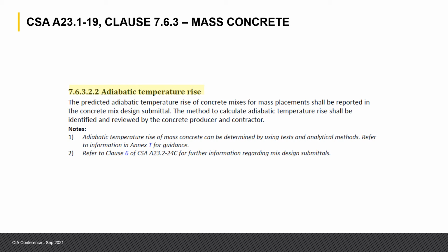So now we have a requirement that the mix design needs to include the adiabatic temperature rise associated to that combination of materials. Even when they do not report the actual proportions of materials, you need to provide the adiabatic temperature rise value that has been calculated. And there's guidance provided for the calculation and testing of that adiabatic temperature rise.